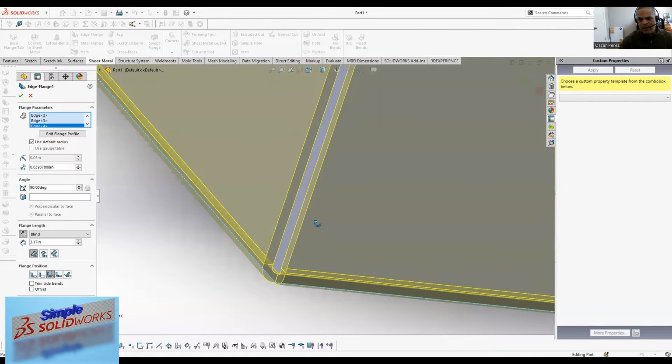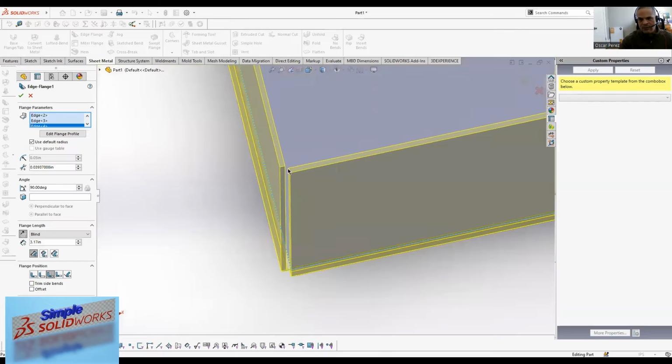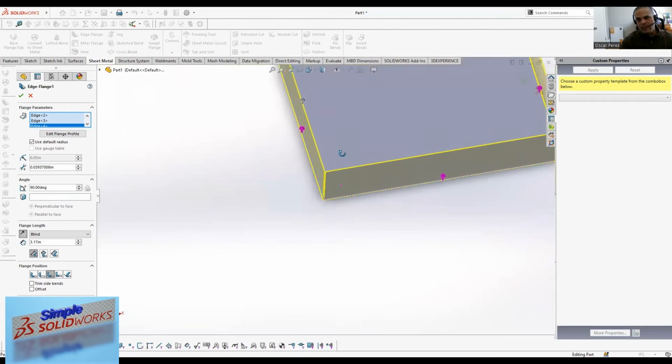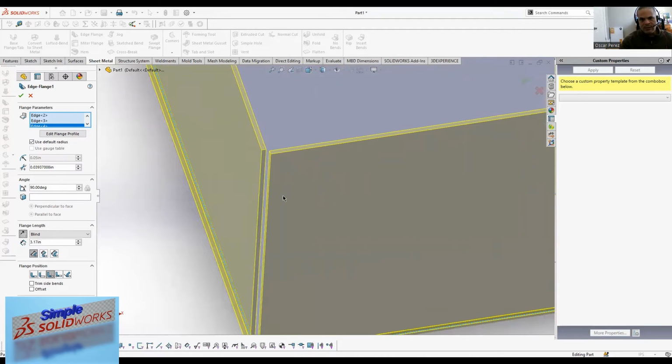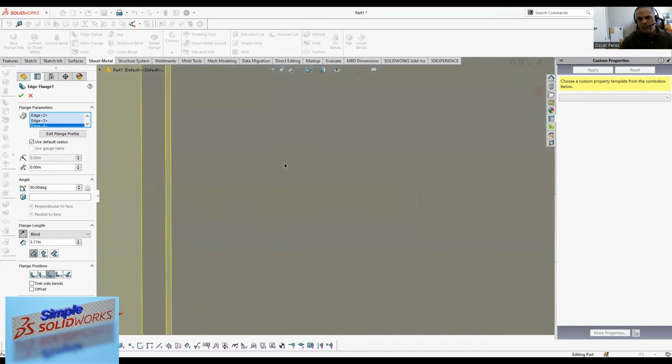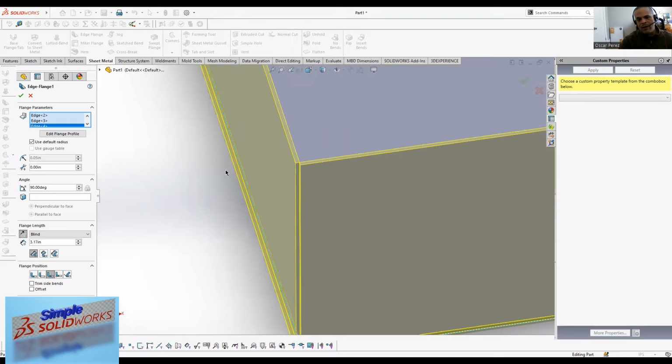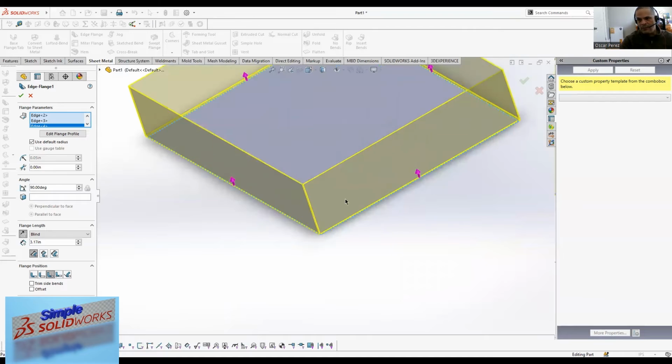So if you have a company that has a very precise way, like some places where the whole extrusion and the whole sheet metal process is done automatically, even the welding of this, then this will probably be too much of a gap distance for that type of process. So if you notice here, here's where it says gap. You can probably just take that to 0, and it's going to take that really tight. You see how it's closed up? And that might be a process where, if you have it all automatic, then that gap distance has already been done.